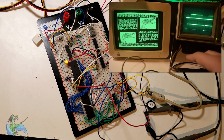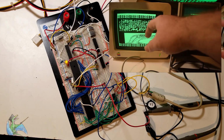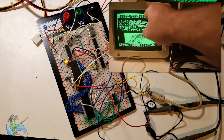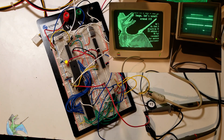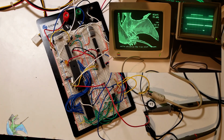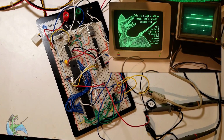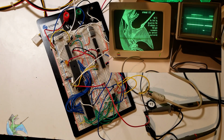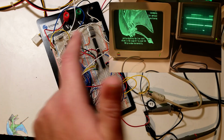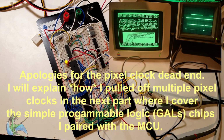Now, one thing you may have noticed is that my board is capable of multiple pixel clocks. See, this is a ridiculously low pixel clock. This is a 4 megahertz pixel clock, and because my original target was for something like TRS-80 or S-100 video, I decided, instead of using a 16 megahertz crystal to drive the CPU and as the maximum pixel clock, I've actually gone with a 12 megahertz crystal.